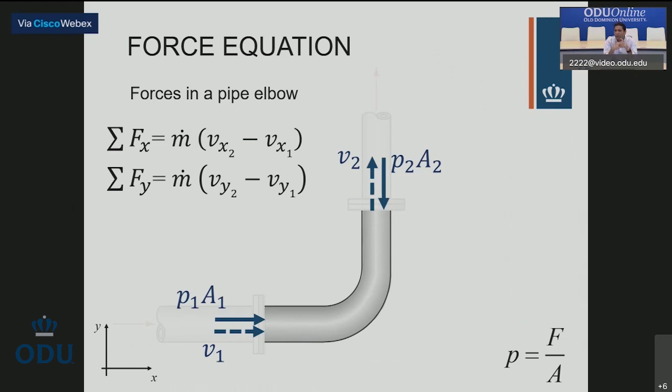Remember that drawing that I gave you about the cylinder, that the force due to pressure is always acting upon the area perpendicularly? So it's acting perpendicular here, but why is it opposing the direction of the velocity? Because my focus is on the fluid in the elbow, not on the fluid in the pipe. So those two forces are acting against the fluid that I'm looking at.